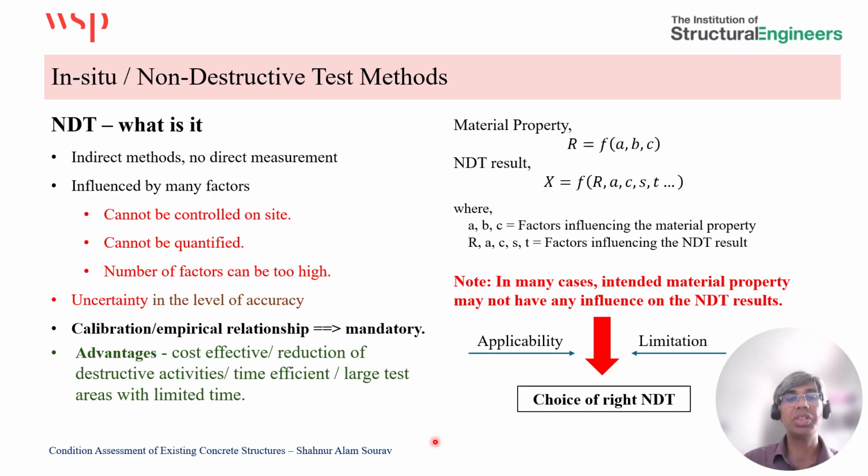We can cover large areas within a limited time to get as much information as possible. As I have already mentioned, in many cases the intended material property may not influence the NDT results, so we need to understand the applicability and limitations of the non-destructive testing we are using. At the end, we need to decide what the right NDT is in our assessment process.